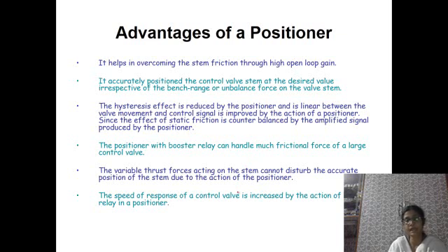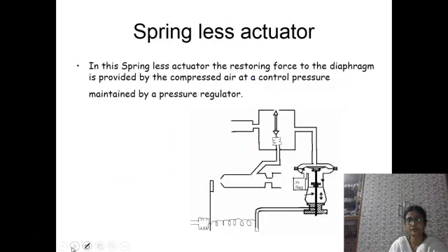Variable thrust force acting on the stem cannot disturb the accurate position of the stem due to the action of the positioner, and the speed of response of the control valve is increased by the action of the booster relay in a positioner. So there are several advantages of using a valve positioner.